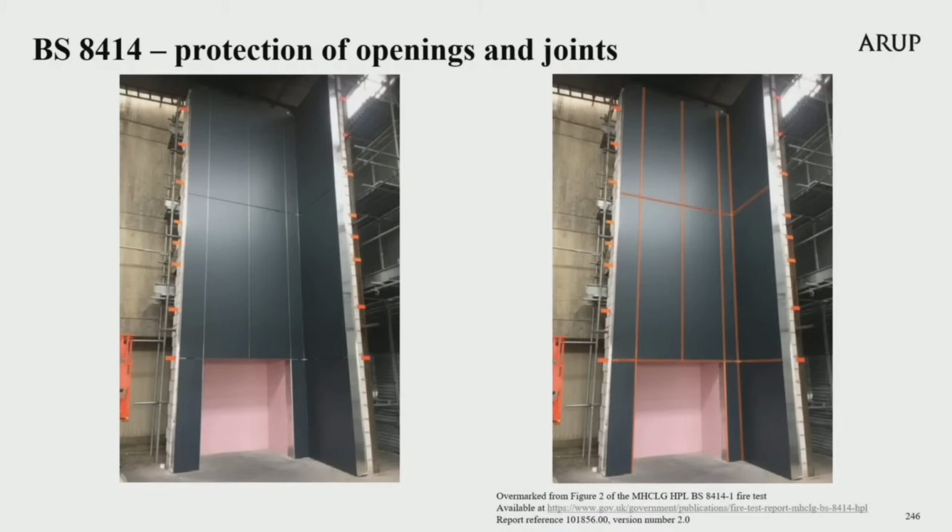If the external cladding system does not offer any protection to openings in practice, i.e. there are no cavity barriers around the openings, then the interface between the test specimen and the combustion chamber must also remain unprotected. This is as stated at Note 1 to the definition of external cladding systems in the British Standard.